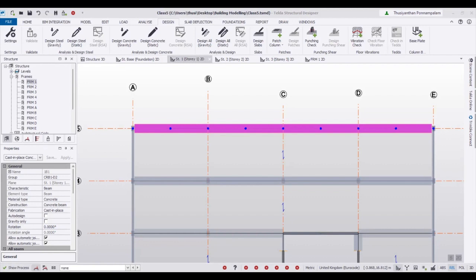Then the good thing is here. You see, right? You calculate the rebar quantity, right? How much H10, how much H16, right? Basically, we have two types of rebar, H10 and H16. It calculates total rebar. So in this particular beam, we want 1740 kg, right? So you don't need to do your own cost estimation and quantity takeoff. It's totally calculated by the software for you, right?